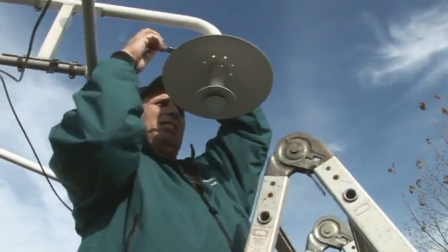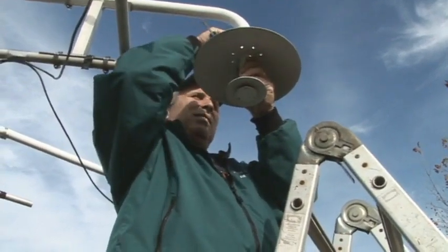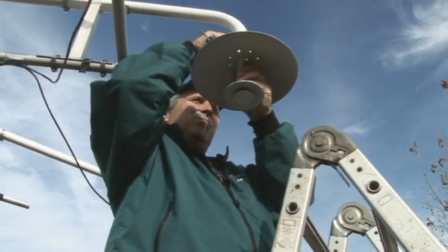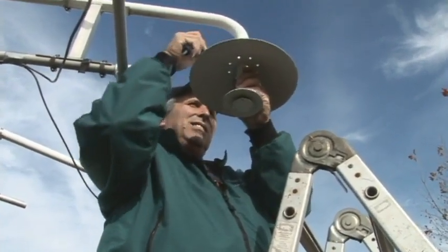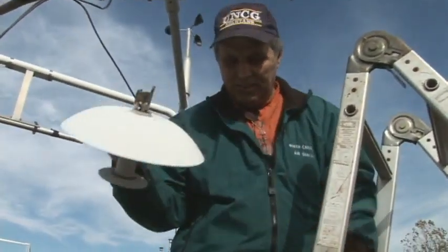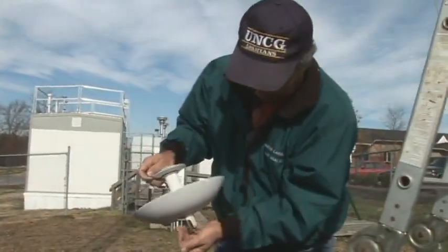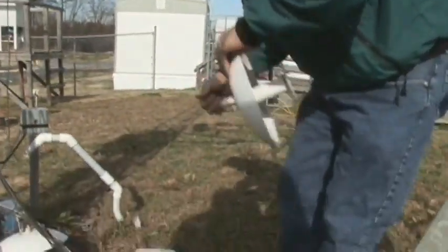At this time, the outside technician is removing the probe from the housing. Care must be taken that the tip of the probe is not damaged. Proceed with caution. Insects may have built nests inside the housing. Once the probe has been removed, it should be inspected for dirt, debris, or damage. If none are found, it is time to perform the calibration.